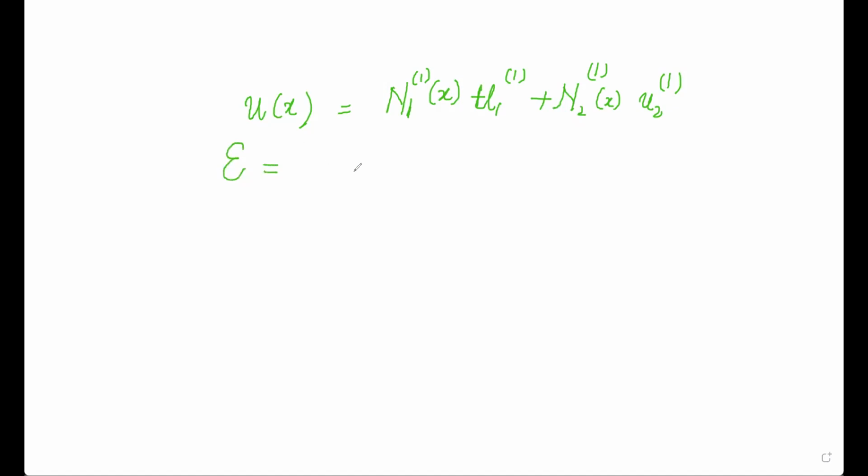So if we write now the shape function, we are writing u equal to N1(x) times u1 plus N2(x) times u2 for element 1. So what will be the strain? That is equal to du by dx.